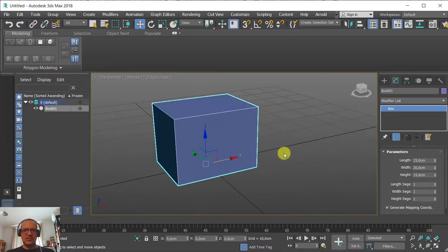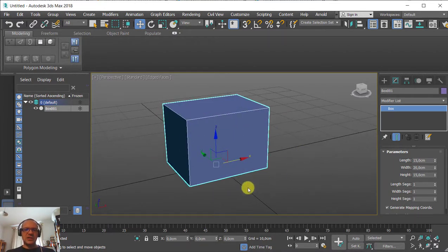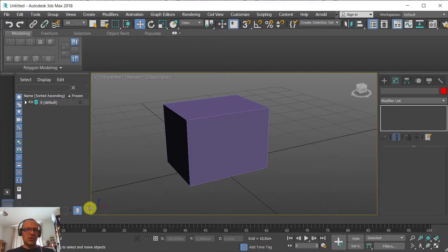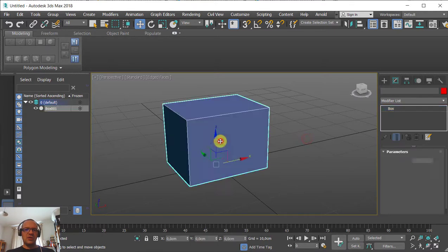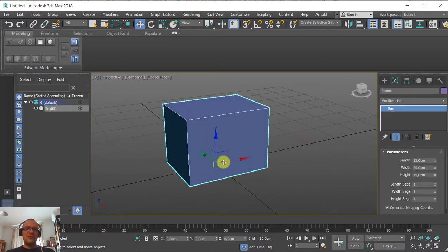the Z direction. And as you see, we have a world coordinate here, and we have this element's coordinates as well, especially when you're choosing this select move. This one will be indicated. If you rotate this item around, there's a chance these two might not match, but this one will always give you an input on the world coordinates.